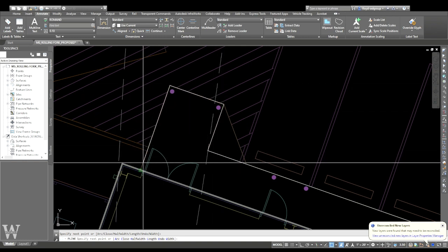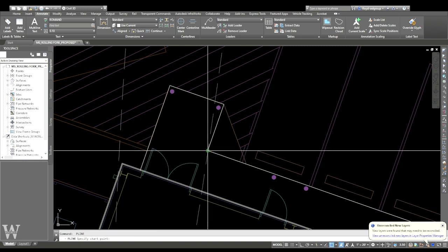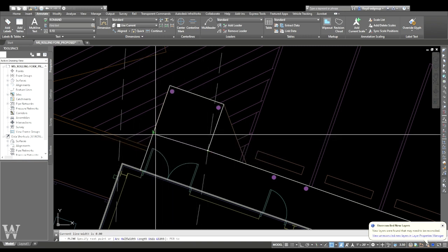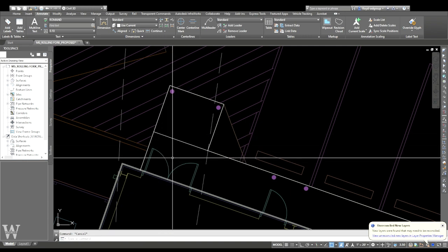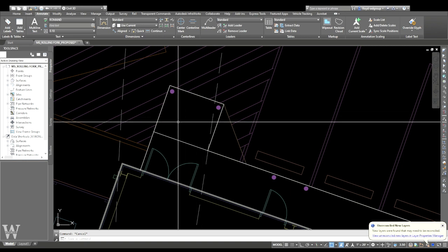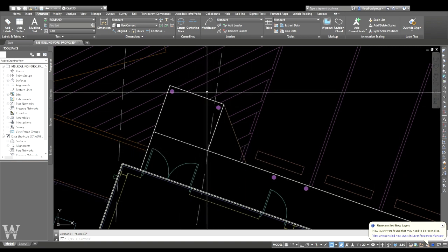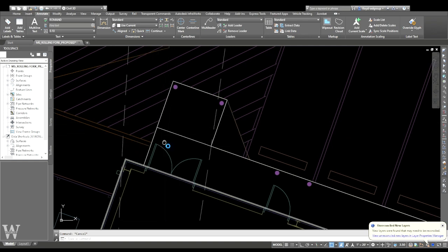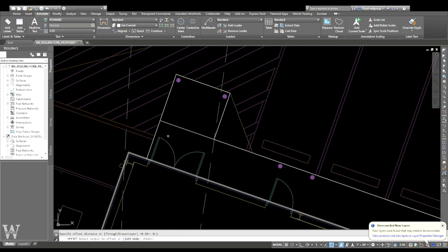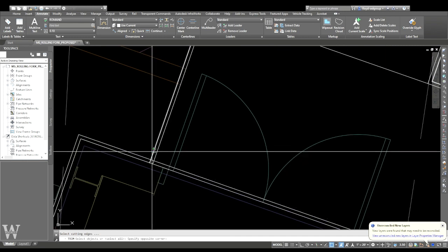Okay, so I'm going to get my sidewalk, and I'm going to put one right here and right here, and I'm going to draw one right here, because in all actuality this is a landing and that's a ramp down to the grade below, because this is all 6 inches higher, and they got to get into the building for this loading dock right here. Okay, now I'm going to go ahead and offset my sidewalk a 1/10, because there will be differences there.